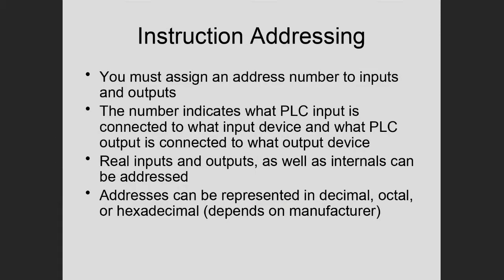Here, addressing is important. Addressing is the way, as I mentioned, we link the screw terminal to your instruction to a particular cell in the input image table. When you do your first lab, you're going to do a tutorial first. When you go through that tutorial, you'll see, when you write the address and connect it to a switch, and you'll see the position in the data table, the input image table, this will all come together and make sense to you. So addressing is important. You can read this slide.